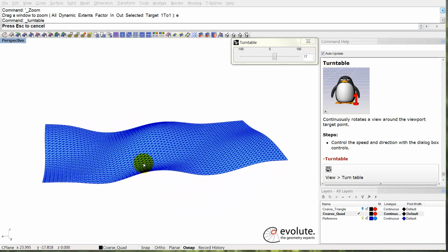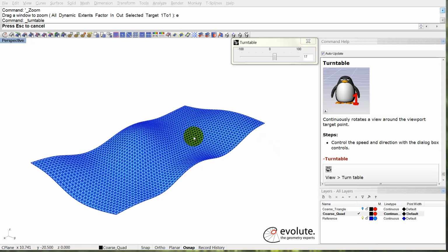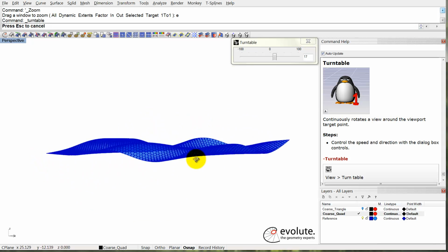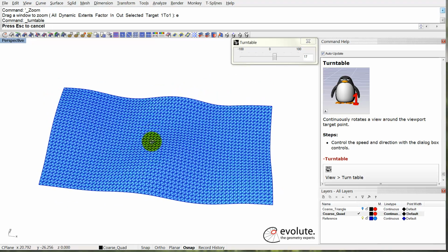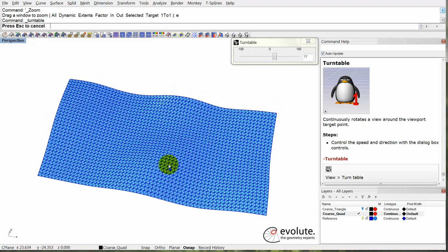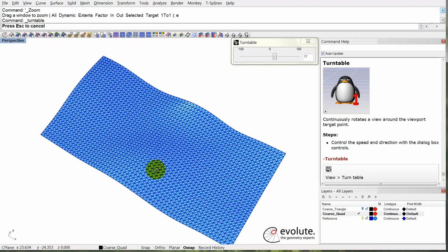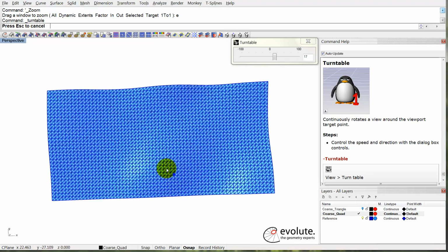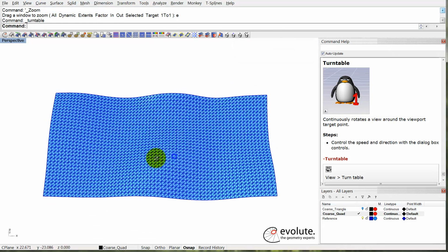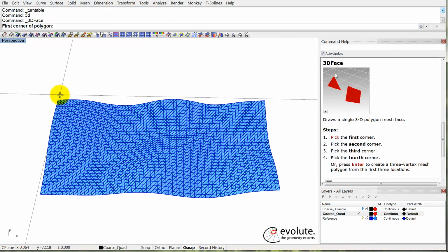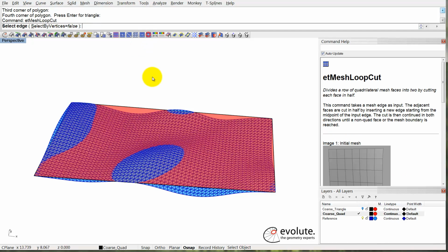It's actually a pretty smooth mesh, and I will want to reverse engineer it into a NURBS patch and do a bit of modeling to get some sharp features over it. For the reverse engineering, I will use EvoluteTools PRO as well. You can actually use the light version. I will just optimize a really plain quad mesh over it, and then I will use that mesh to build a NURBS patch over it.